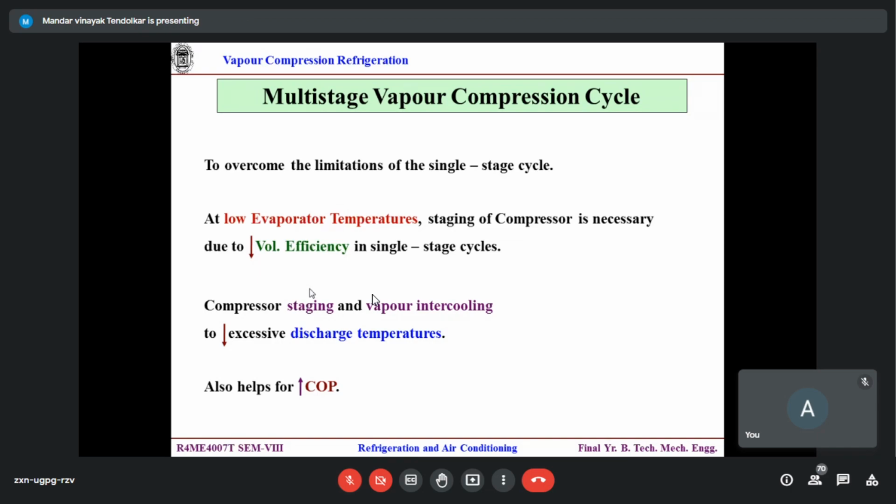No, adiabatic will have more work. Isothermal compression is the process that requires the minimum work. Adiabatic will naturally take maximum work because you are not allowing any heat transfer. So the isothermal compression process is the ideal one, ideal in the sense of minimum work requirement. The moment you deviate from the isothermal one, you need cooling.